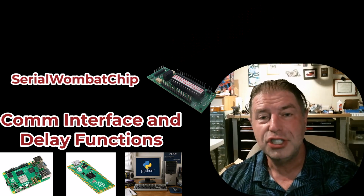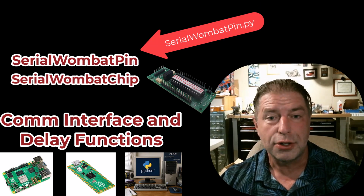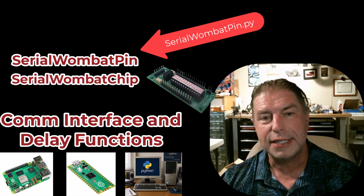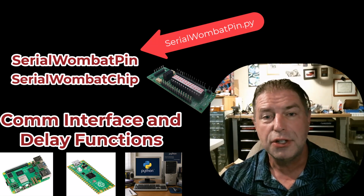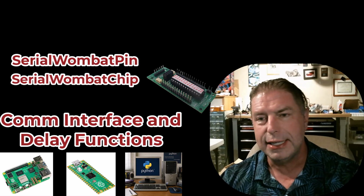The Serial Wombat chip has a variety of pin modes that run at 1 kilohertz. Each one is its own state machine. There is the Serial Wombat pin class. It handles things like setting or retrieving the public data for that pin, and generic pin functions like, say, setting them to be weak pull-up or open drain, things like that.